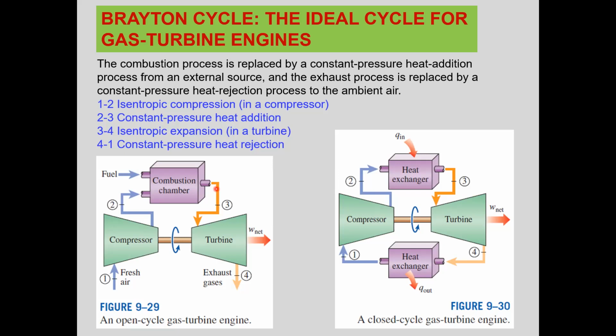And these combustion gases are at high temperature, and they are also at high pressure because air was compressed before, so in the combustion chamber pressure is the same, it doesn't change, theoretically, ideally. The combustion gases are at very high temperature and high pressure. They enter the turbine and they do work against the turbine blades.